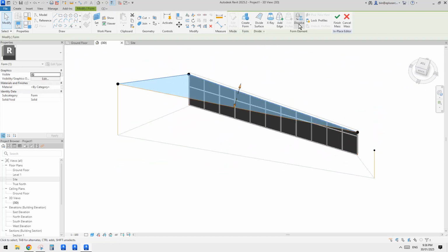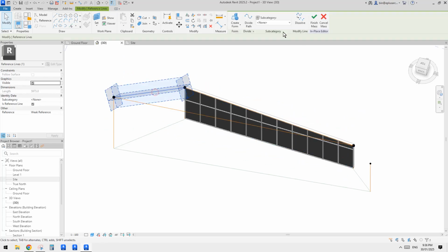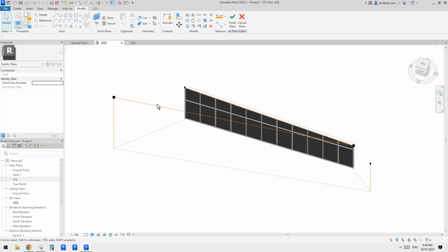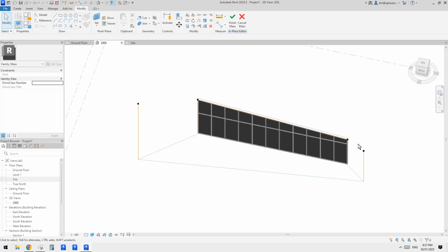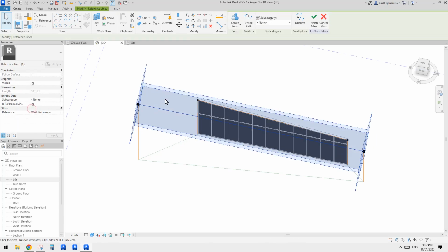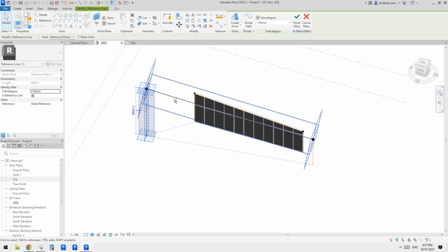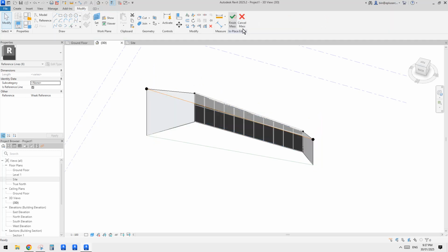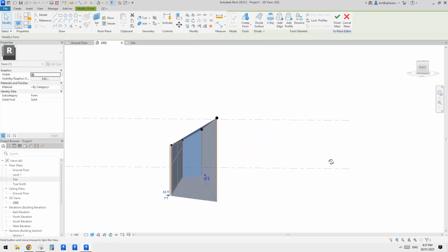Okay, and then we can get rid of this. We don't need this anymore. We don't need this anymore. Dissolve. Just make sure you only select one reference line. Dissolve it, and then we can just connect these. So select these 2 points, create a spline through point, make a reference line. So now we have 2 sets of reference lines. One, and also the other one here. So now we can create a form, and this time this surface is flat.